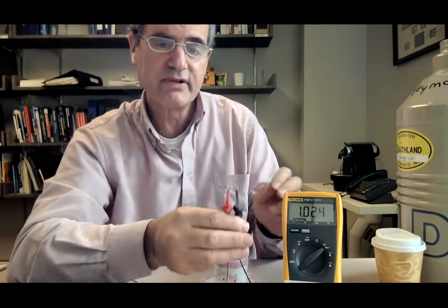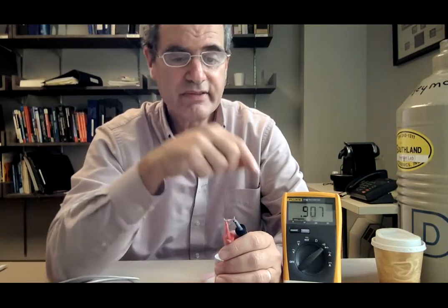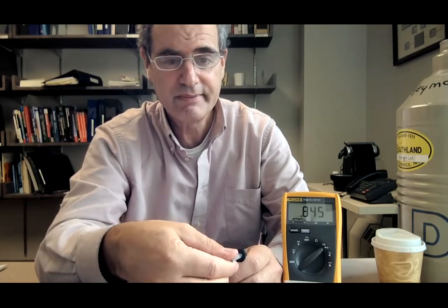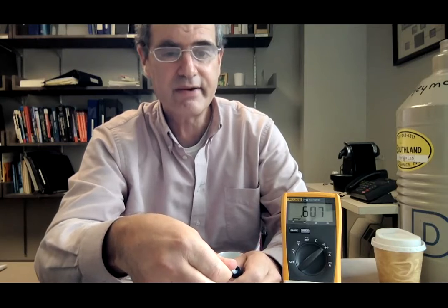However, at room temperature, the voltage was lower. All right? I've taken the diode out now. It's warming up. And you can see the threshold voltage is getting smaller as the diode heats up. I'm going to heat it up in my hand to accelerate this process. And then pretty soon we'll be back down to the value at room temperature. Okay? There we go. Okay, well that's what I wanted to demonstrate for you.